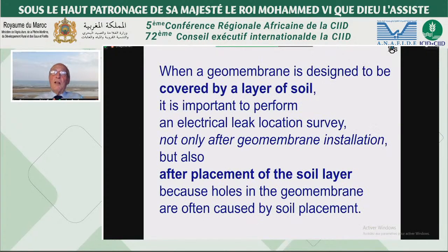Now, when the geomembrane is designed to be covered by a layer of soil, it is important to perform an electrical leak location survey not only after geomembrane installation, when the geomembrane is still uncovered, but also after placement of the soil layer, because holes in the geomembrane are often caused by soil placement.